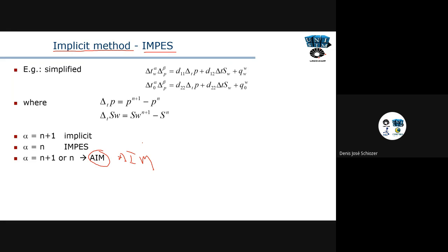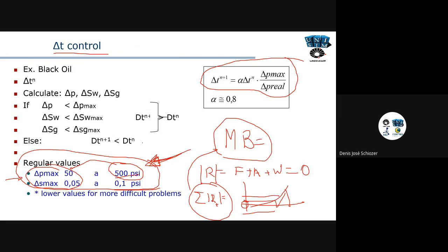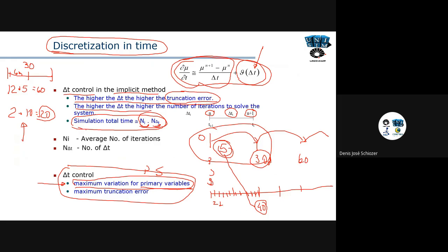can simulations optimize the iteration number? No, I mean, the iteration number is a function of their tolerances, okay? So it will calculate iteration 1, 2, 3, or 4 until it reaches a tolerance. So we cannot optimize the iteration number. We normally try to optimize the size, this simulation time here.